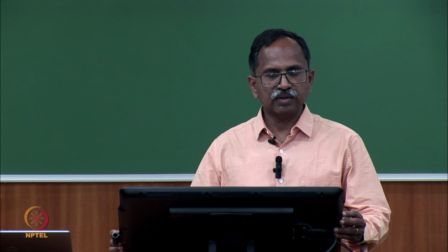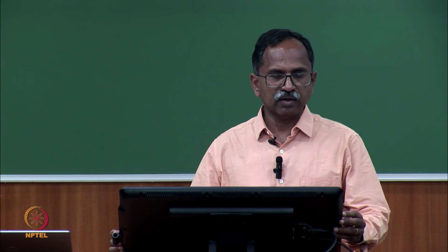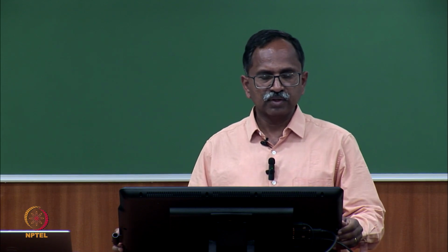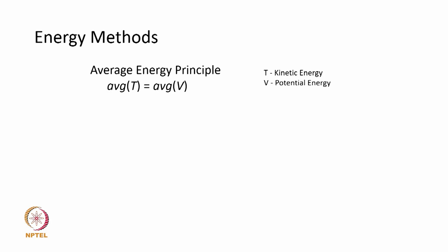If you remember, the steps in carrying out vibration analysis on any mechanical system involve first converting the physical system to a simplified vibratory model, like a spring mass dashpot system. From that, we derive governing equations of motion by using the Newtonian approach. That is the most convenient way, because we know how to get a free body diagram, identify the interaction forces, and then apply Newton's second law.